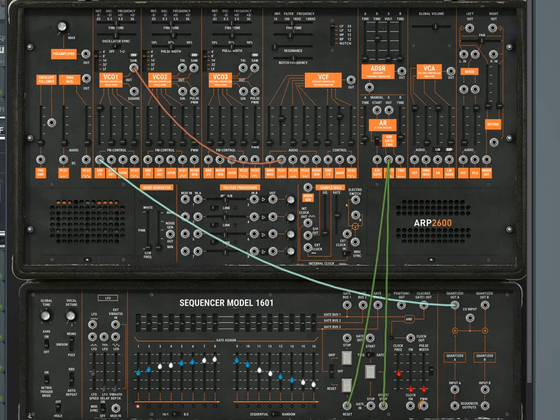And the sequencer stopped. So what's going on here? A gate is a signal which is initially off, and it comes on as soon as I press a key. And it stays on until I let go of the key, and then it goes off. And so if we switch back to gate, this means that we want the sequencer to respond to a gate signal. We want it to start when we press a key and stop when we let go of a key.